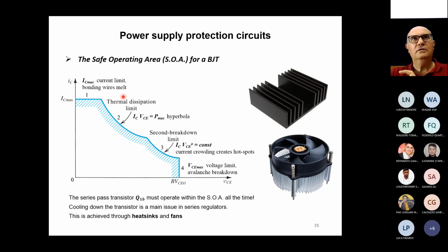The power dissipation through the thermal resistance of the chip, of the device, gives the temperature increase in the device. I don't know if in some of your subjects you studied something about thermal propagation. Basically, you can define a chip, a die to ambient resistance.